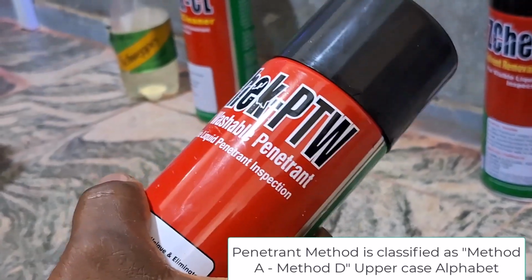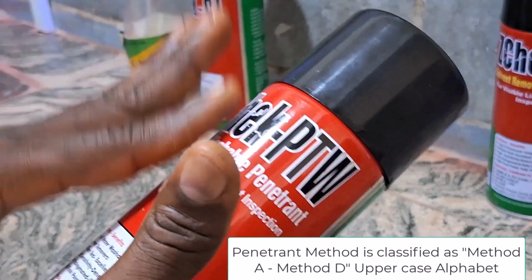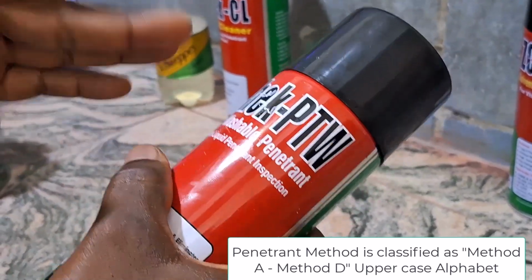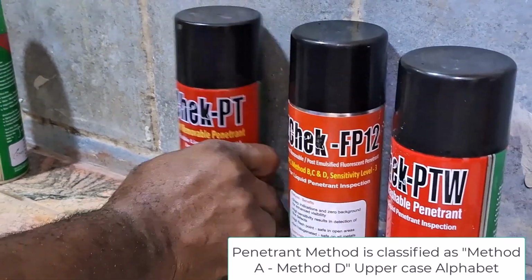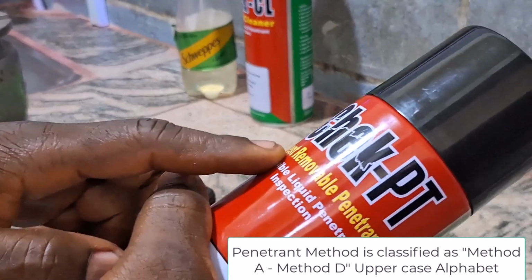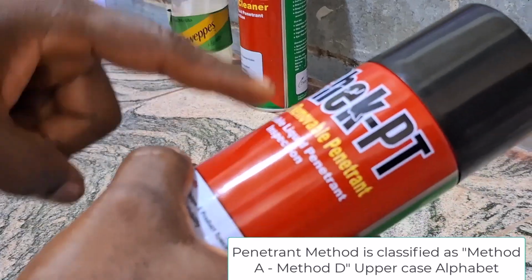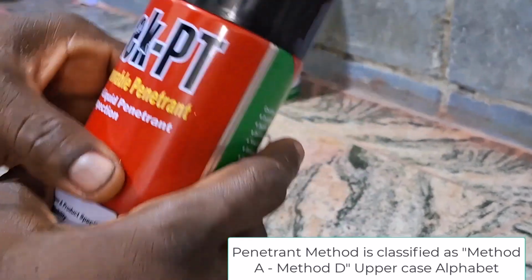That is type 2, method A. You can only remove excess penetrant by using water to wash it off. Then the next one is your solvent-removable, which is your type C, and this is for visible. So in this case, we have 2C. So the technique will be 2C.